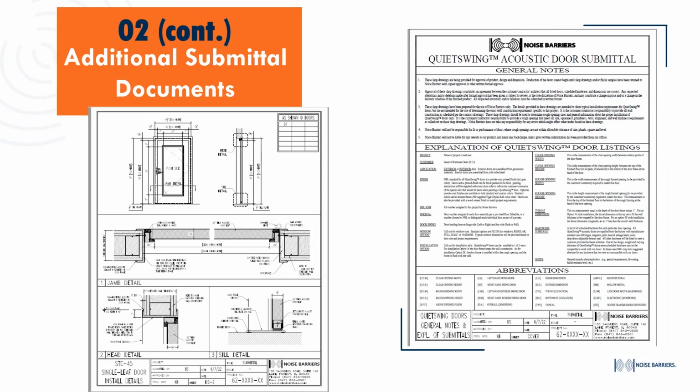And then there's a couple other pages. One, to make sure everybody understands the definitions that we're talking about: what do we consider a rough opening? What is a throat dimension? This page goes out with the submittal. And this second page is really a 1A on that first one because it's critical for the rough opening and the rough opening framing. We specify what the rough opening is supposed to be, and where at all possible, we're given a partition schedule and we will show how we want that rough opening reinforced.